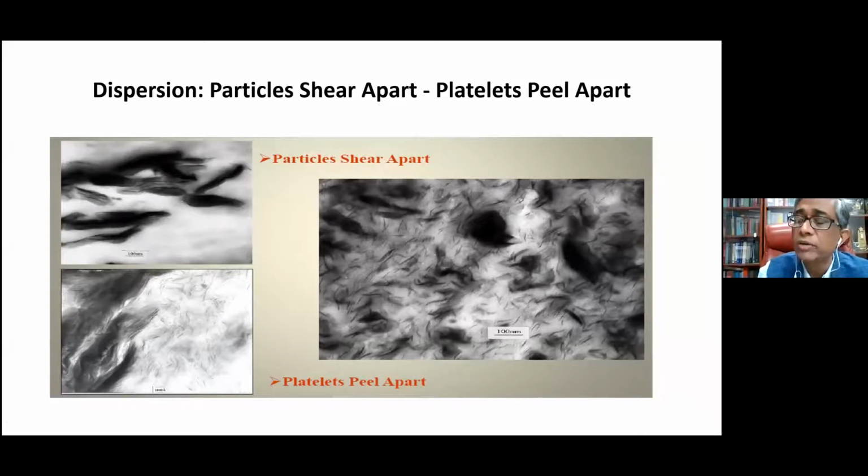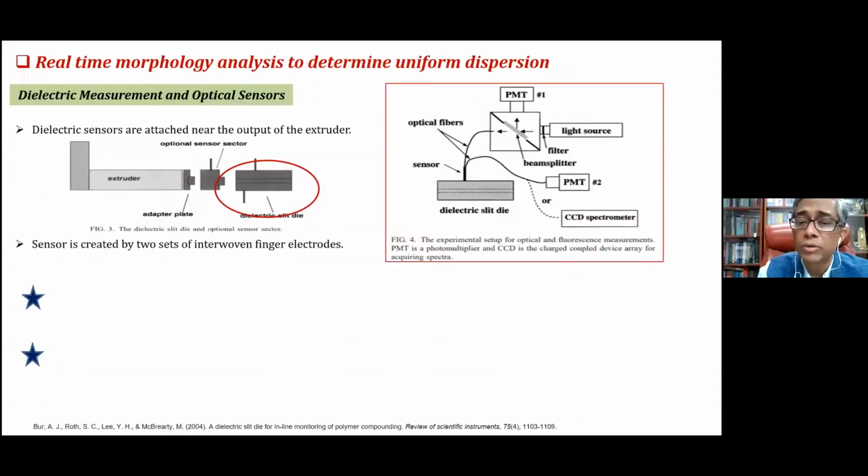But there are technologies nowadays that we can utilize, and we can measure this. I wanted to give an idea of how we know. Like in regular master batch, I know how it has been mixed. Now the technology is coming up. One more thing I would like to mention: for nanofiller mixing, not only shear and elongation, you need sonication also. You need a very high level of sound energy for vibration, to peel off these nanoparticles in such a way that polymer and nanoparticle mixing happens.